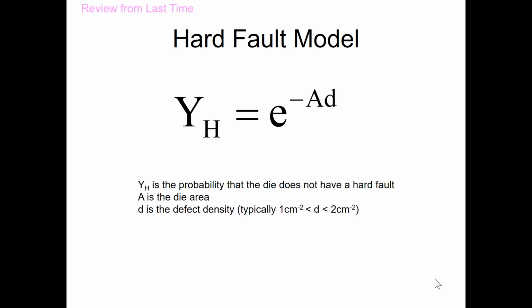So there's some unfavorable trade-offs between yield and area, and that puts a fundamental limit on how big our areas can be in a die. The reason I'm going to stop with this model is that it's not our goal in this course to try to accurately predict yield characteristics or fault models. This is close enough that it tells you about what's going to be going on.